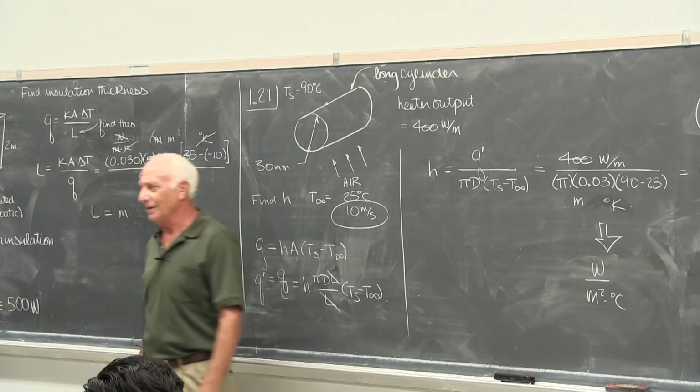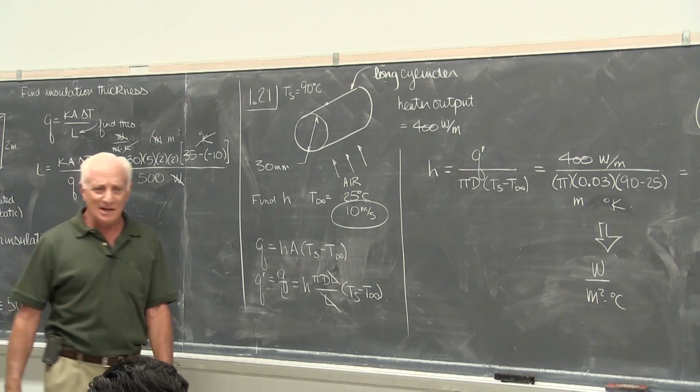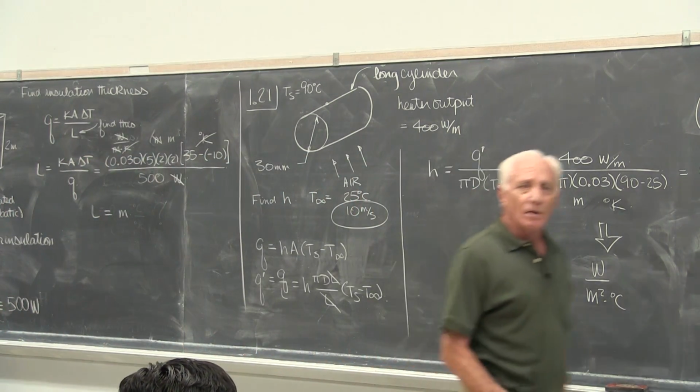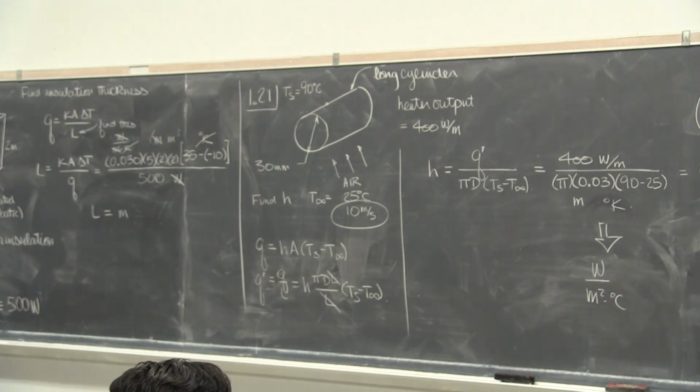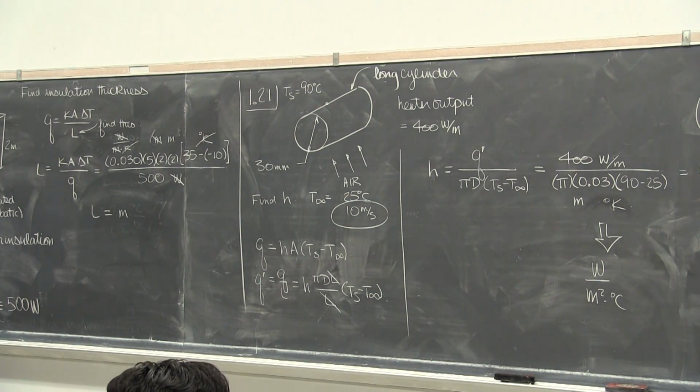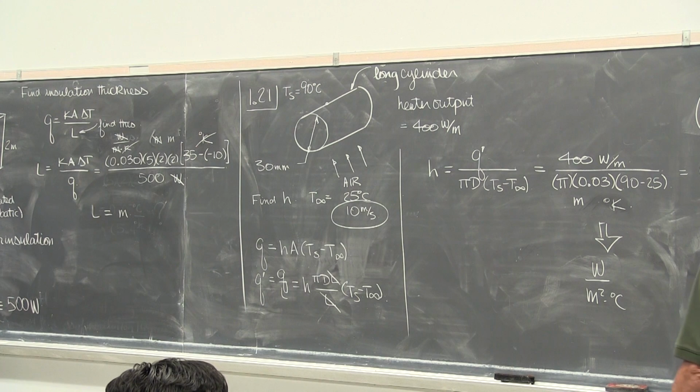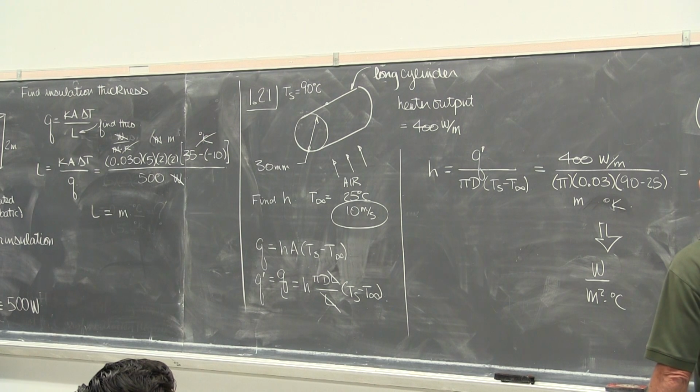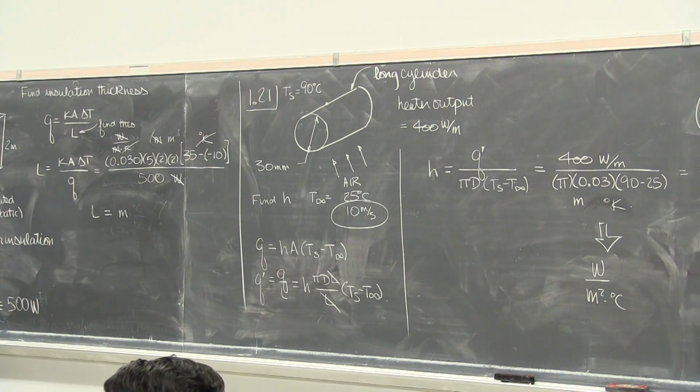Drive some people crazy. They say, whoa, whoa, whoa, you can't do stuff like that. Don't you have to add 273 to degree C to get degree K? Well, if you give me a temperature in degree C, I do. But if you give me a temperature difference, I don't. Boiling point of water. Freezing point of water. Wow, isn't that interesting? It doesn't make any difference.